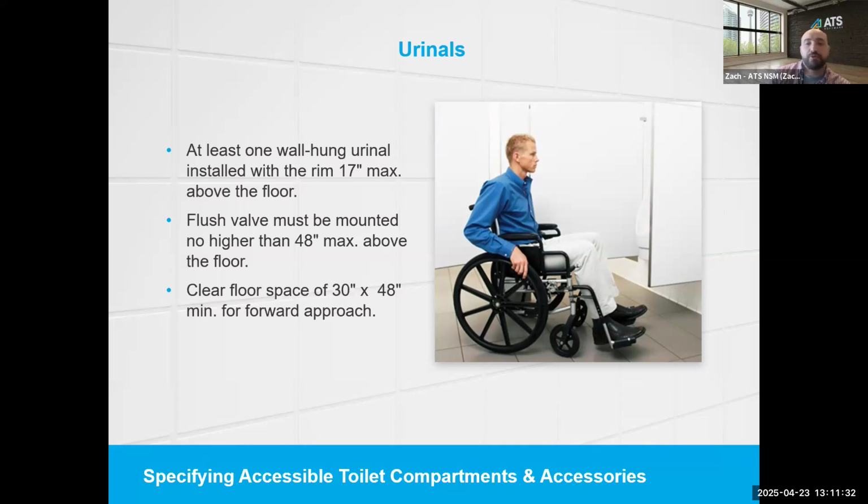Question on surrounding the grab bar and the minimum clearance, the 1.5 inch minimum clearance there. There's kind of two questions that go hand in hand. One is the minimum clearance of the 1.5 inches from the underside of the grab bar or the center line of the grab bar. It's 1.5 absolute clearance would be the plane of the wall or the panel, and it would be the center of the grab bar. It would be the center of the diameter of the grab bar.